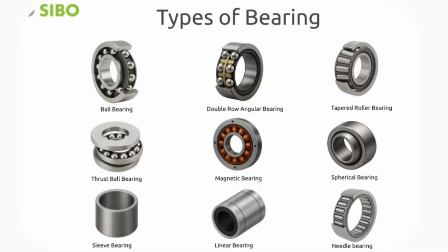An overview of mechanical bearings categorized by their design, motion, and load handling capabilities. 1. Ball bearings, rolling contact. Ball bearings use spherical balls to reduce rotational friction. They excel at high speeds but handle lower load capacities compared to roller bearings because contact is concentrated on small points. Deep groove ball bearings: the most common type.